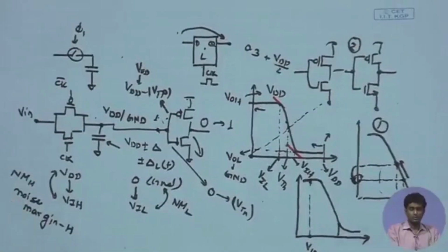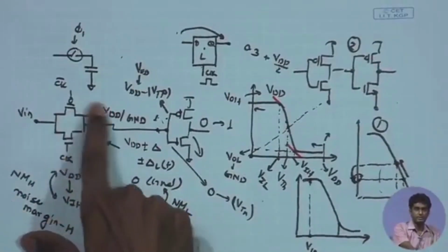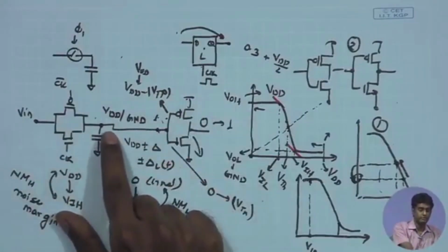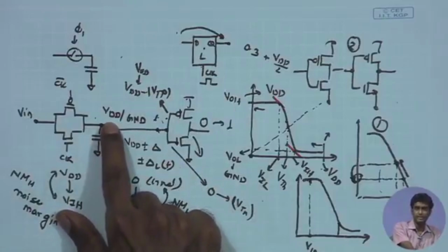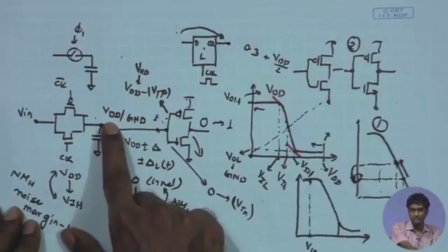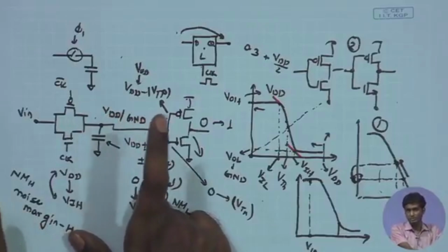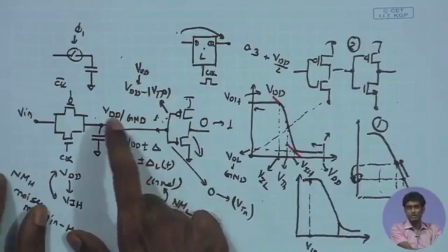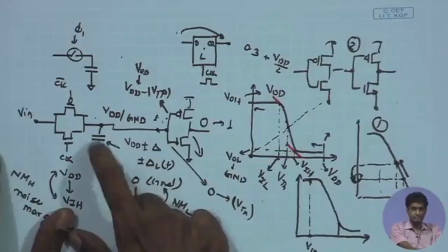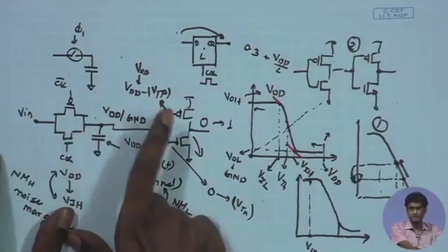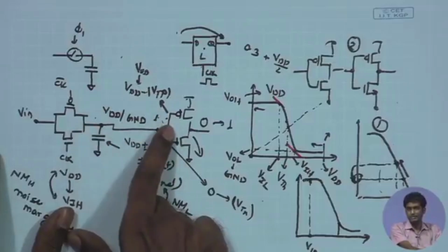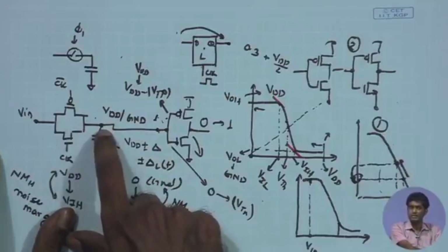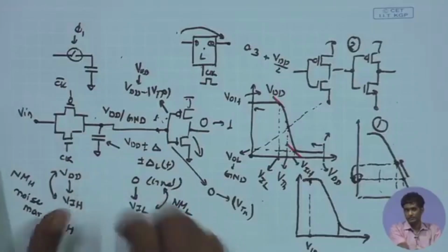So, this is also going to give us an answer about the design of the digital sampling, how it is different from the analog sampling. When you are talking about analog sampling, this has to be very precise, we cannot even tolerate a millivolt of drop as we have seen, but in the digital case we are much more relaxed, we are not even worried about 100 millivolt of drop, and therefore, of course, we may not even need this sampling capacitor, we can just use the parasitic capacitance of the next gate for sampling the digital value, because the voltage is so large and we are concerned with only VDD or ground.